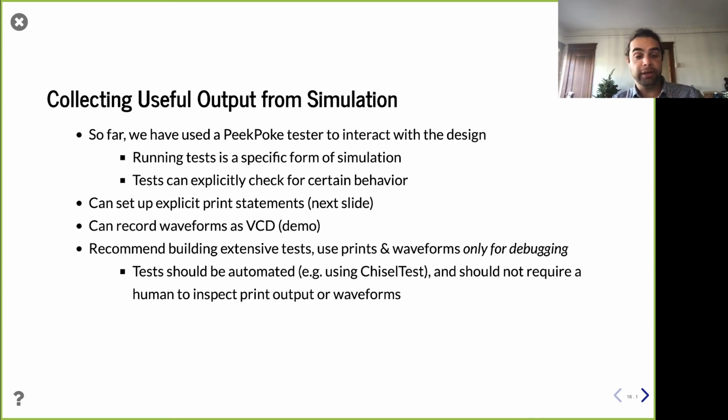Much more common for hardware designers, which we're familiar with, of course, are waveforms, right? Waveforms are a way you can see visually all the values of your design over time, and it makes it very easy to debug things and go through it. The waveform format Chisel produces is called VCD, and I'll demo that in just a second. And you can go ahead and see the values of your design.